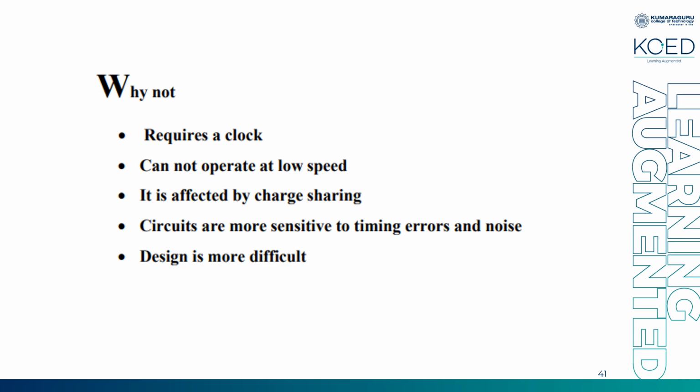If a single timing is missing, even a small nanosecond change, the output needs a 0 to 1 transition, and based on that 0 to 1 transition, the next circuit decides when to turn on and off. So even a very small change in design will collapse the entire working of the bigger circuit. So the design has to be more careful. So when we go for complex circuits, it's more difficult. So that's all about your dynamic logic.